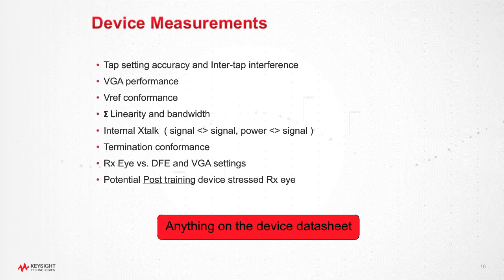Does it feed back X millivolts to a summing junction if it sees a 1, and Y millivolts when it sees a 0, or does it just apply some sort of gain, a dB-based spec? Going in, there's a linear part, which could be a variable gain amplifier or CTLE. It's got various knobs that need to be set. That'll show up in the data sheet.